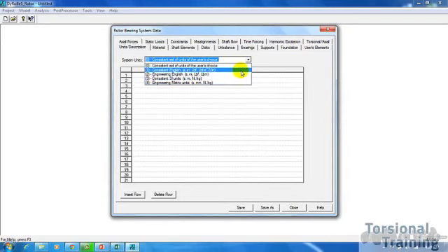One is the classic consistent English units, which is seconds, inches, pound force second square over inch. Engineering English, which is pound force and pound mass being the key differences, and then consistent SI units with meters and kilograms and newtons, and engineering metric units, which replaces meters with millimeters. So depending on what your preference is as far as units go, you can pick either of these options. I personally like to work in consistent English units because that's typically what we use here in the United States.